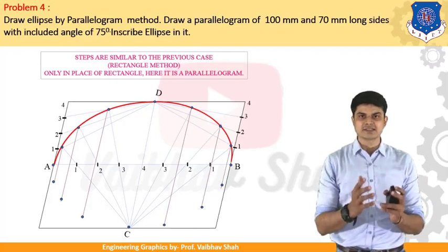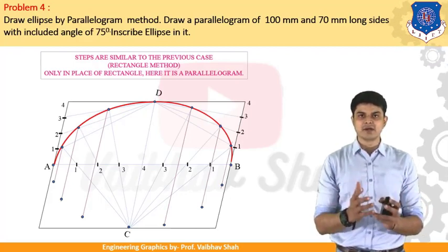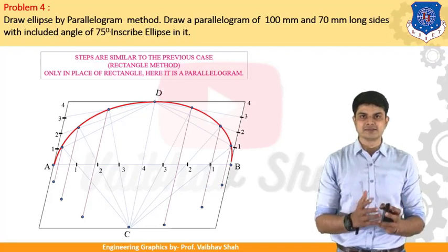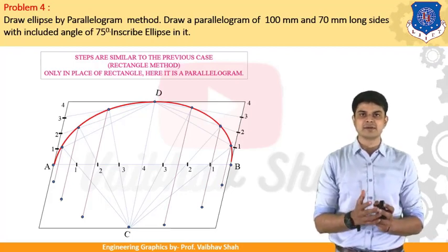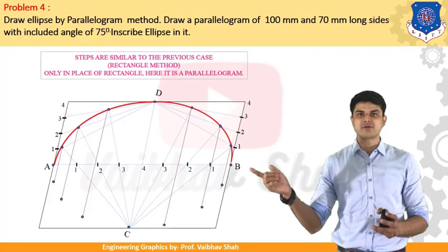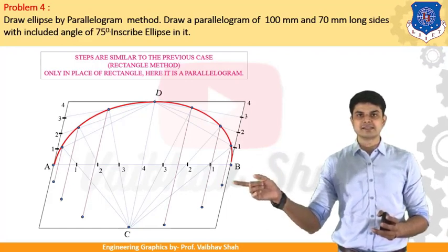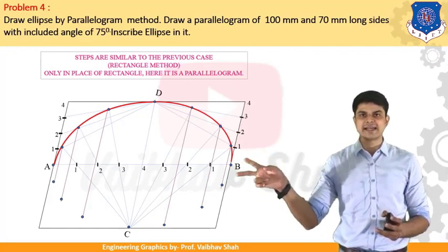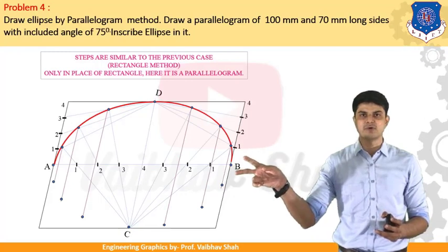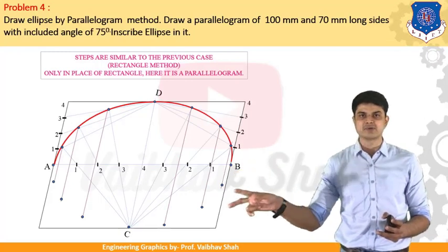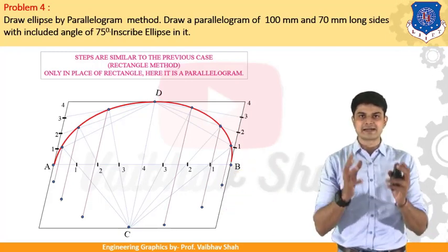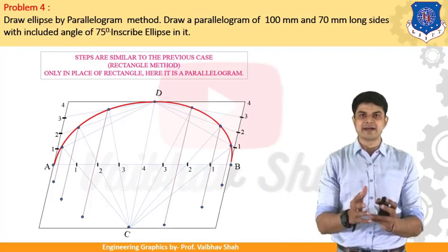Now this line must be at equal proportion from your center line. Let us suppose I take one example. See, this is the line starting from your center axis till your 1 point. So you need to take the dimension of that line, and you need to produce the same dimension from your center line in the downward direction onto that line, and you will have the end point as your ellipse point.